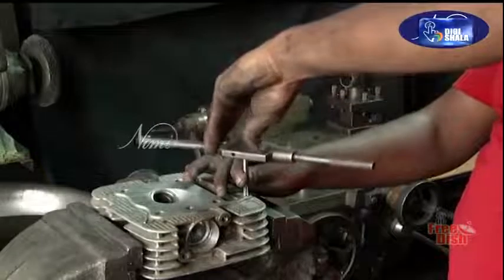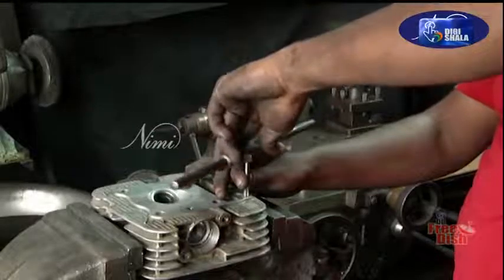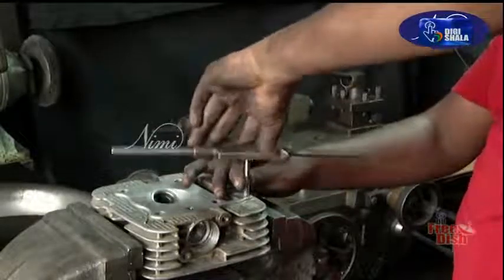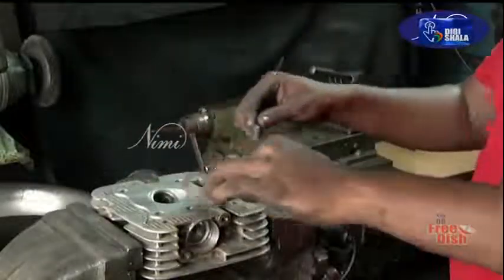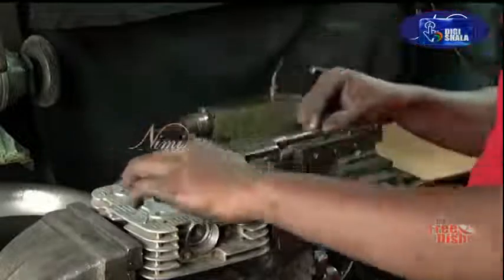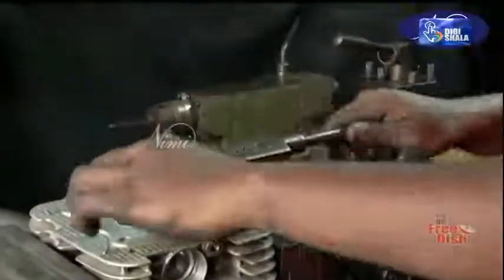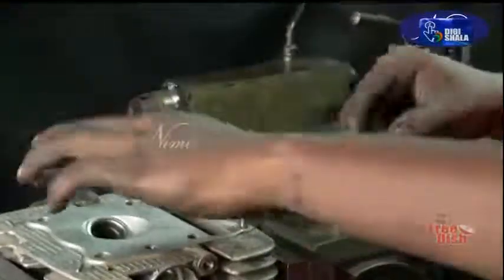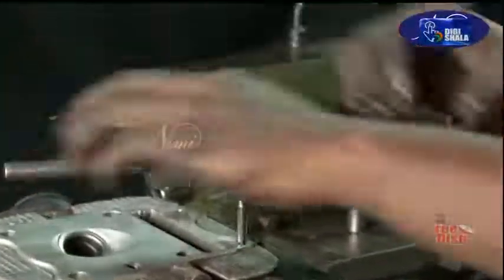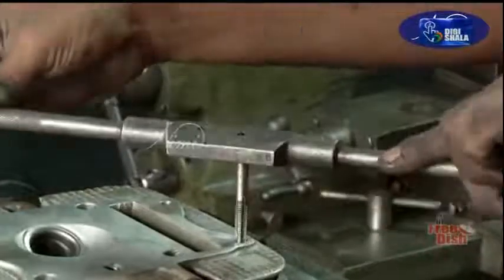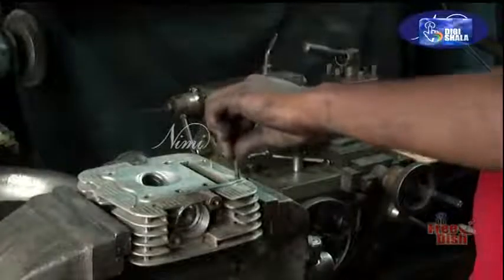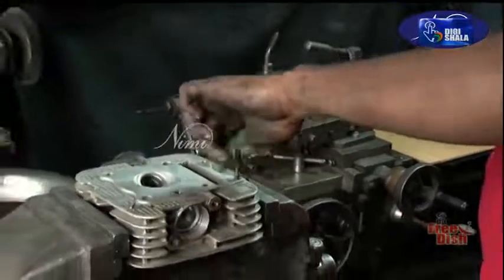Set the easy out stud extractor on the drilled hole. Turn it anti-clockwise by tap wrench. As the easy out penetrates into the stud, the grip increases and gradually the broken stud portion unscrews. Replace a new stud in position after lubricating the threads.